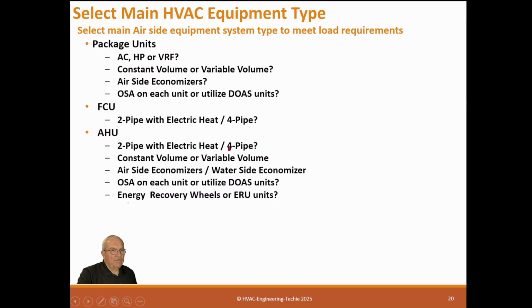One problem you always have in design is whether you have more horsepower on the water side or more horsepower on the air side. What I'm trying to say is, if you do a job with fan coil units, you'll actually have more horsepower on the water side than you will on the air side. If you use large air handlers, you'll actually have more horsepower on the air handler side. So you have to kind of see that. Where all that horsepower is in a project will affect your process on how you want to control your energy.